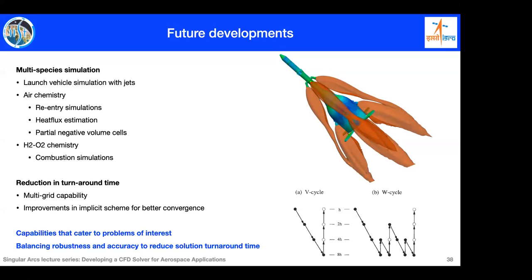I have another question. Since you mentioned combustion simulations, those typically have multiple time scales. You have one time scale for your flow, whereas your chemical reactions will occur at a much faster time scale. So your equation system will become very stiff. So do you only go ahead with implicit schemes in that situation? Yeah, we usually go ahead with implicit only, but there are certain additional under relaxations involved. For the additional equations for species, you can have additional under relaxations, but an implicit scheme is usually sufficient.